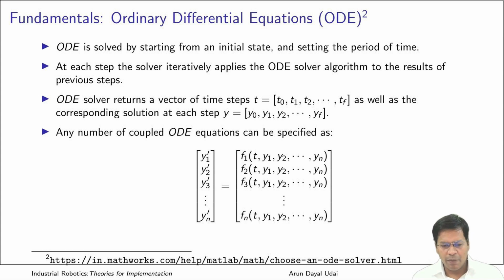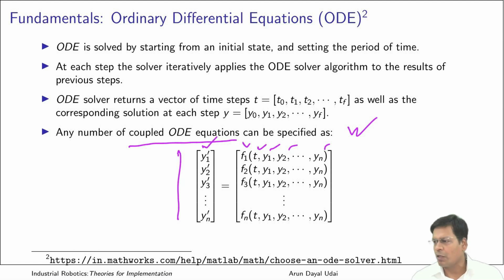Yes, a number of coupled ordinary differential equations can be specified and solved simultaneously in MATLAB like this. They can be packed like this. These are the independent functions of t and the derivatives of y that go here. So they are all different functions. They are all coupled ODE equations which have the same input variables and one output variable. Not basically the input and output variable, basically these are the derivatives. Got it? So this is how it can be expressed. This is all a set of first order equations.